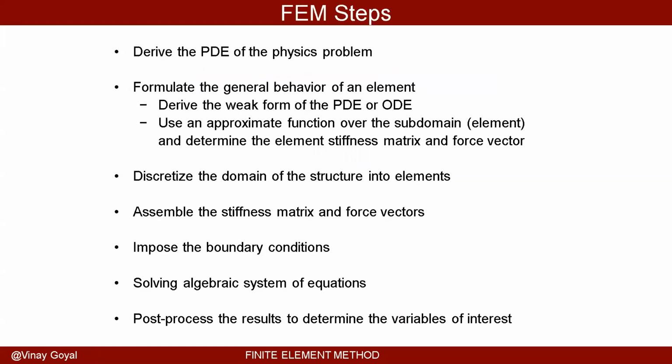What are the finite element steps? We need to derive the PDE, the partial differential equation. From there, we need to formulate the general behavior of the element by approximating the solution to the partial differential equation over the subdomain, which we have called element. We need to discretize the structure now into elements, and then we will assemble the stiffness matrix and force vectors, impose the boundary conditions, and finally solve the algebraic system of equations. And once we do that, we can then post-process the results.